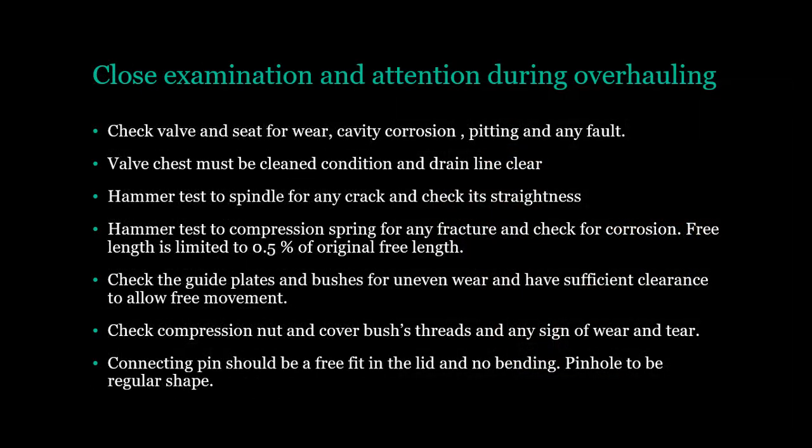Close examination and attention during overhauling. Check valve and seat for wear, cavity corrosion, pitting and any fault. Valve chest must be cleaned, condition and drain line clear. Hammer test the spindle for any crack and check its straightness. Hammer test the compression spring for any fracture and check for corrosion. Free length is limited to 0.5% of original free length.